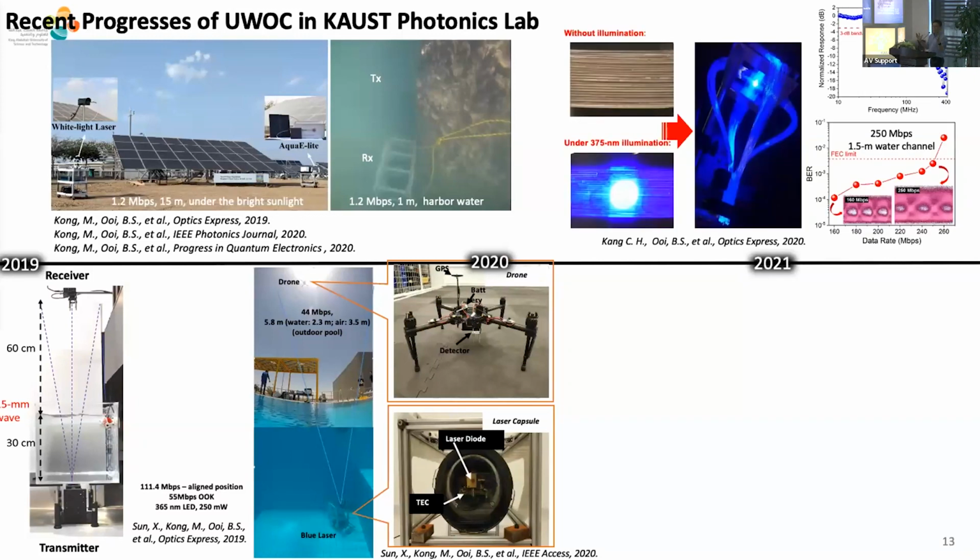Expanding the field of view is always of interest in free space optical communication and also underwater comm. In this case, we developed our own technique that is based on optical fiber. You can imagine optical fiber as a wave optical wire. It guides light. If we have a scintillating fiber, we can put it up as a curtain. When light strikes the surface of the scintillating fiber, the light will be converted into different color light and then guided to a very small photodetector, so that we are able to have a very high bit rate, yet a very large detection surface. So that is the goal of the entire work.